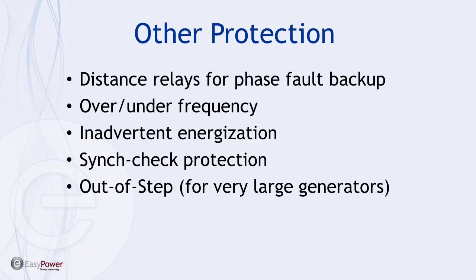All right, some other protection you may run into, and that's typically provided as an option or built into a lot of the new multifunction relays: some kind of distance protection as a backup phase fault detection. This is going to be similar to the voltage restrained relays that we talked about, but you just use a distance element looking back up into the system to detect faults.